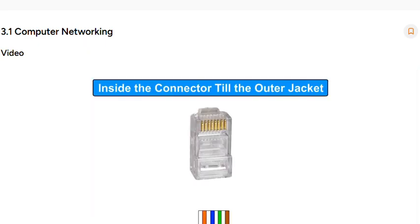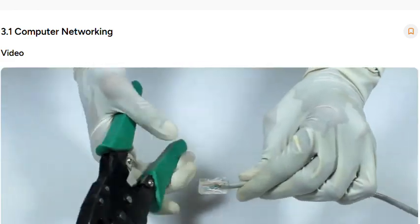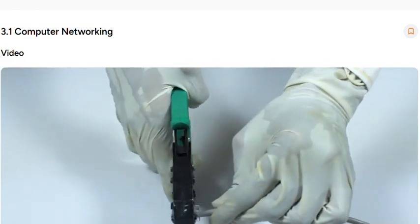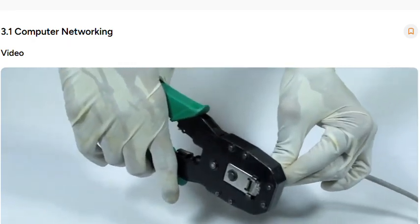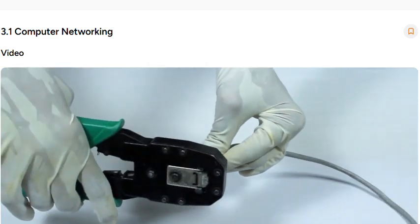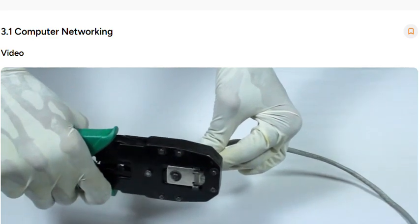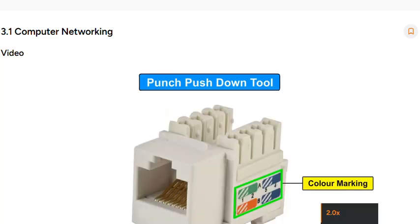Press the cable further inside the connector till the outer jacket goes inside the connector as it provides strength to the cable. Now insert the connector inside crimper by holding the connector and also make sure wires do not come out from connector pin. Now you can see connector pins are aligned in the crimper. Press both the crimper levers on side line under type B.